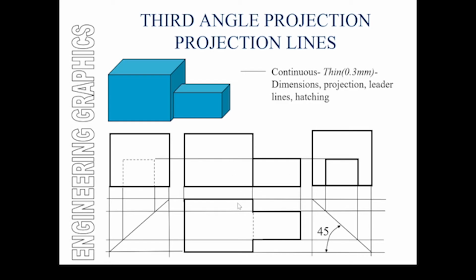As I probably have said before, these views remain connected to each other. So whenever you produce an orthographic drawing on a piece of paper, either manually or using a CAD system, you should expect to have a connection between those. So for example, these lines will remain collinear, and the relationship between that and that is at 90 degrees. So everything is 90 degrees around here as well.